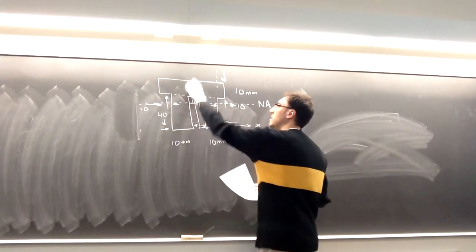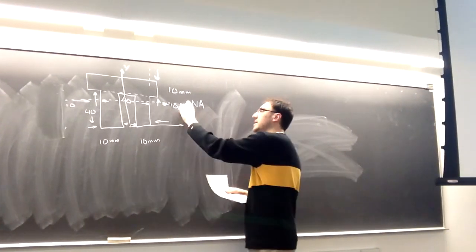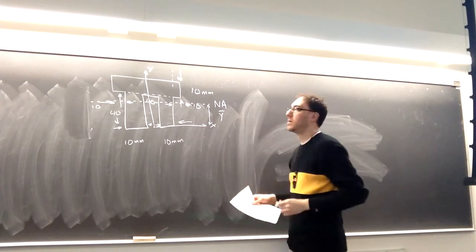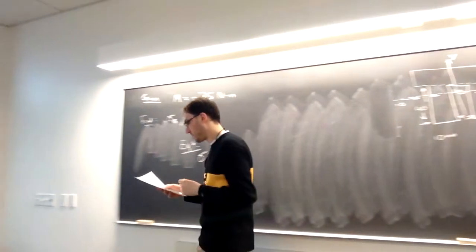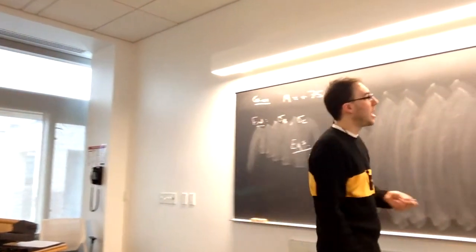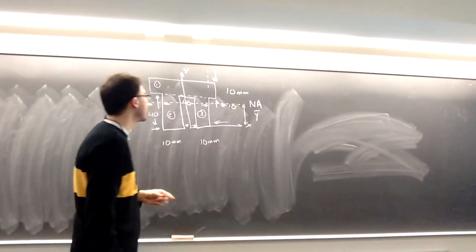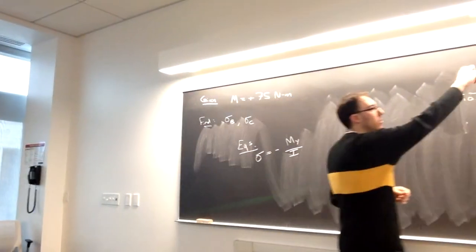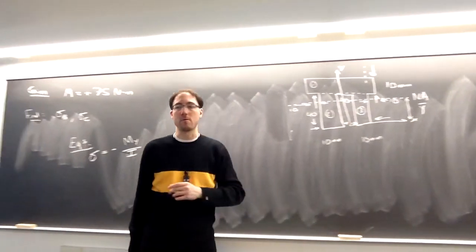I'm going to assign my coordinate system with its origin at the bottom here. So the distance between the neutral axis and the horizontal axis, that's going to be my y bar. That's how do I get to my centroid? So remembering back to 211, I want to break this shape into easy to identify pieces, in this case rectangles. So I'm going to make one horizontal rectangle across the top, and then two vertical rectangles, 2 and 3 here.